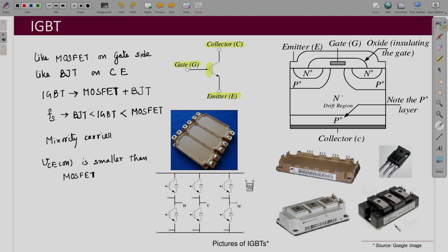Okay. This is another module, and these are those 3 terminals that you can see over here, and there you have these 2 gate emitter terminals as well. So, these are your gate and emitter terminals for 2 of those IGBTs, and this is your collector emitter for one of them, and the collector emitter for the other one. So, those are the ones that you can see here, collector, emitter, collector, and this is another emitter, like that.